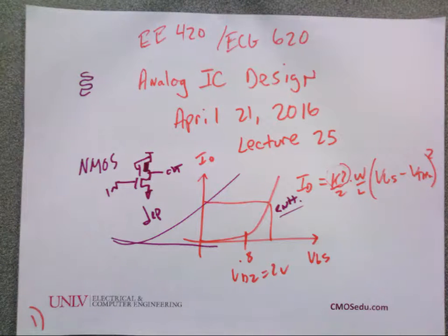For my project, I was using PMOSs for current sources instead of doing the... You mean a diff amp that's a PMOS diff pair? Yes. And at the last lecture, we were saying we could put the extra couple on the bottom and shorten our lengths, and it would be the same. That way we don't have to have the resistor. Yep. So whenever I did that, my curve for my open loop gain completely flipped.